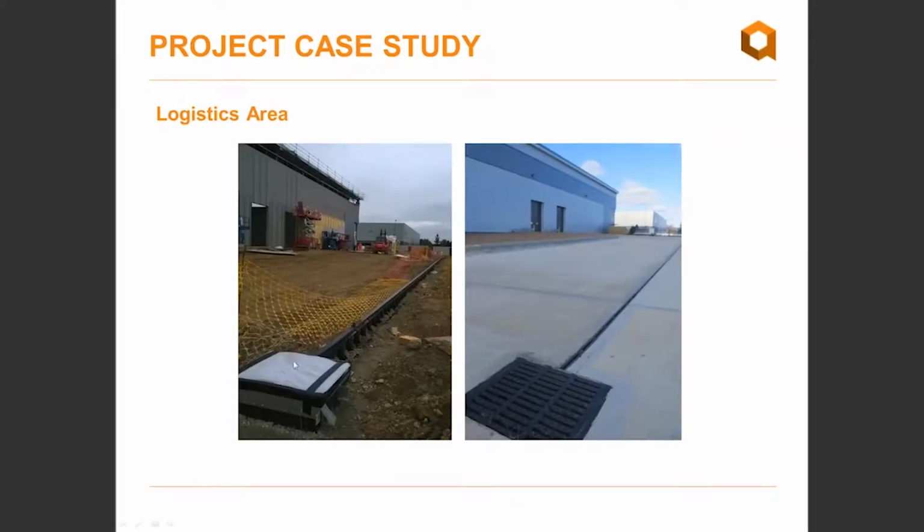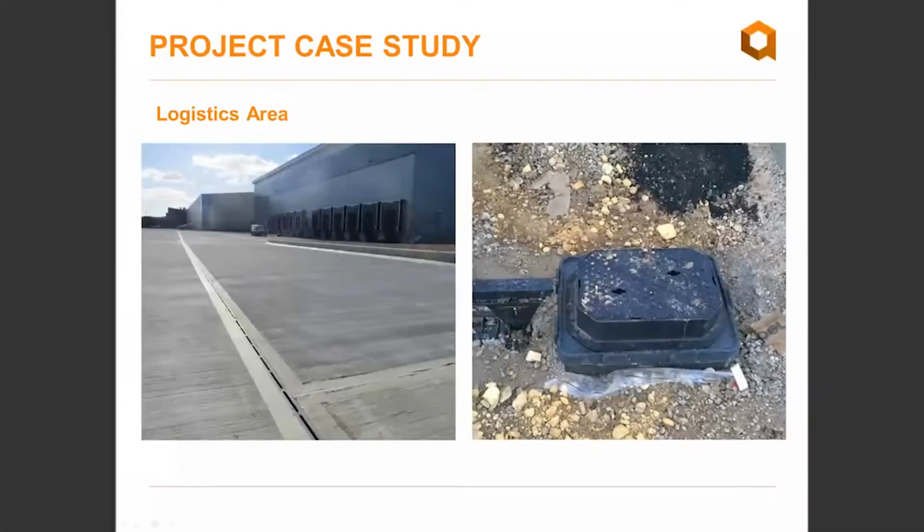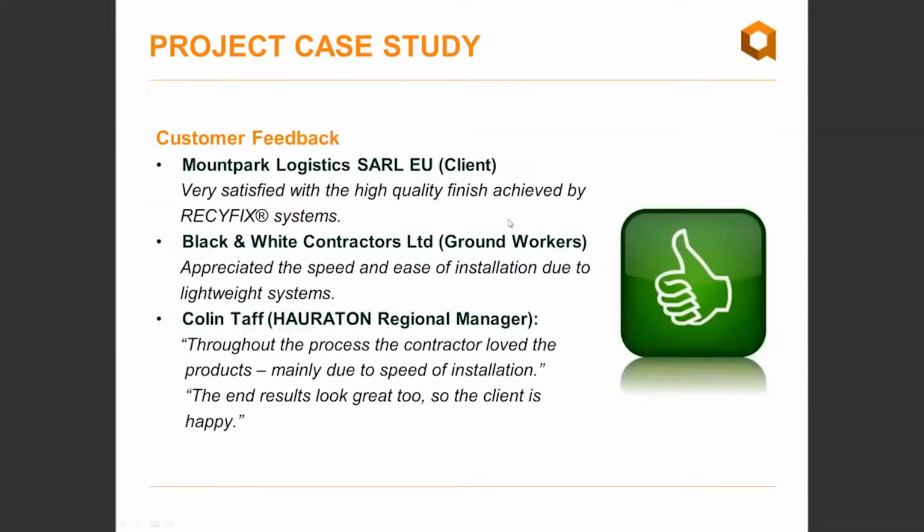What they've done here is they've protected the ductile iron while they were pouring concrete, and again similar mid-installation and finished installation in the same position. And here you see an access point with these slot drain systems. Obviously, you need to get access into the system, so you do that by going in through the access unit and also the catch basin.